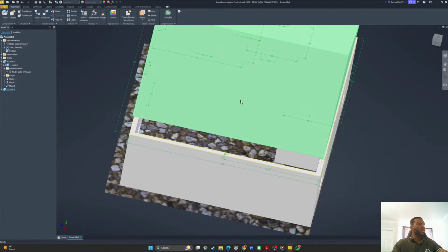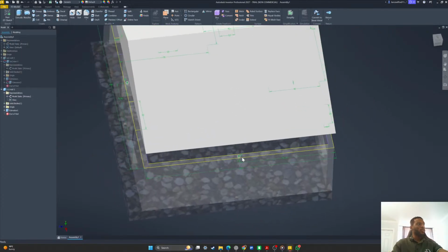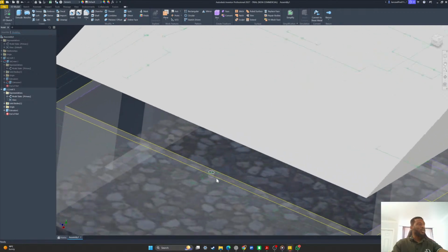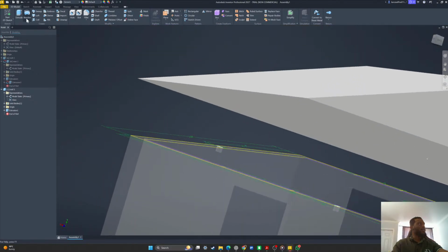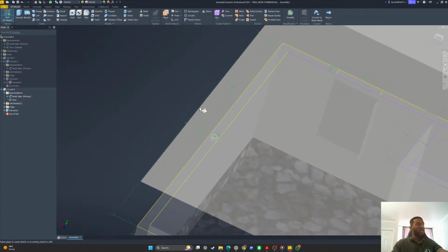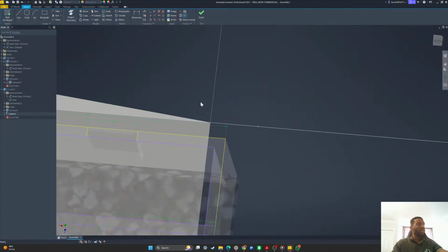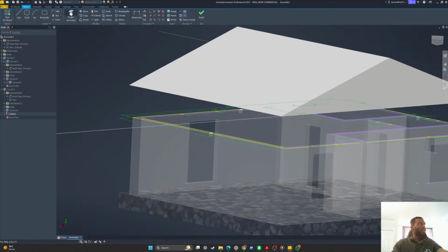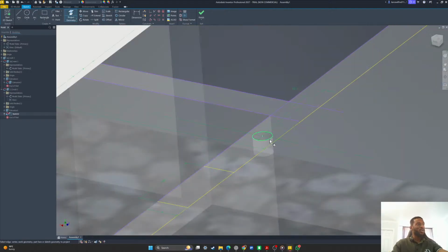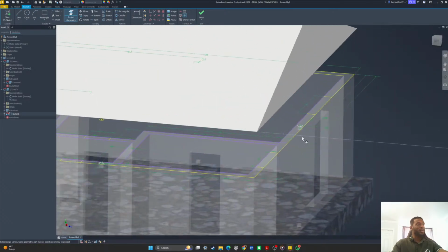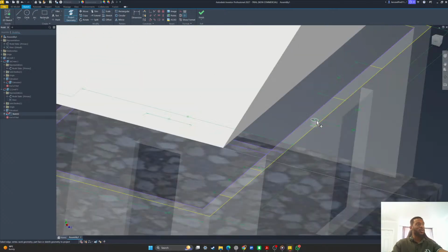We're going to do the same thing for the roof and project these holes onto this part. All we have to do next is create a sketch like so, and then project these geometries right here. Project these circles as well as these as well.